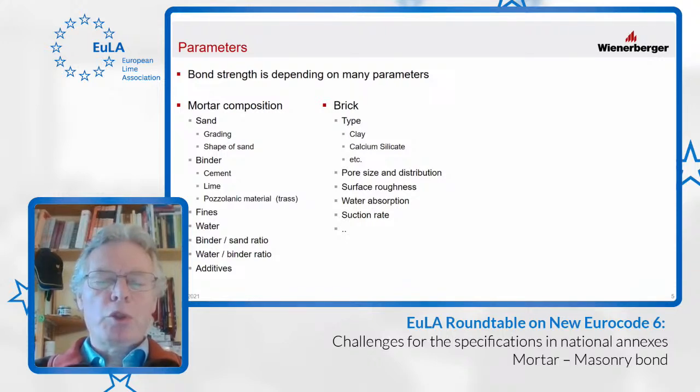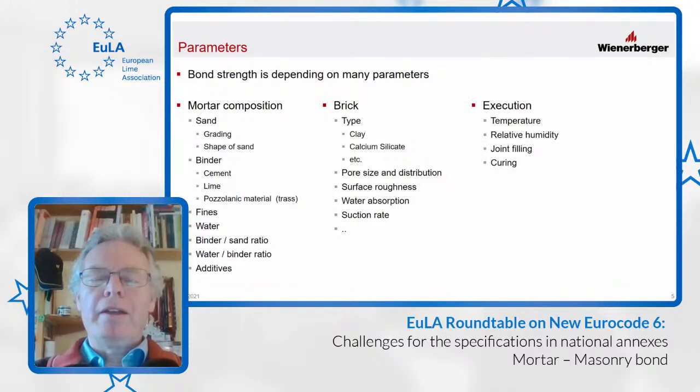Of course, the water absorption, the suction rate, plays an enormously big role. And also execution: what kind of temperature do we have at the time of execution? The relative humidity plays a role. How well are the joints filled, the workmanship, the curing afterwards? Is it done at all? All those factors play a role.